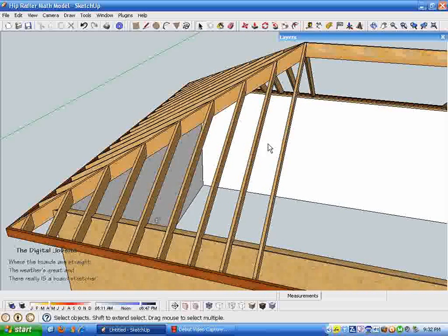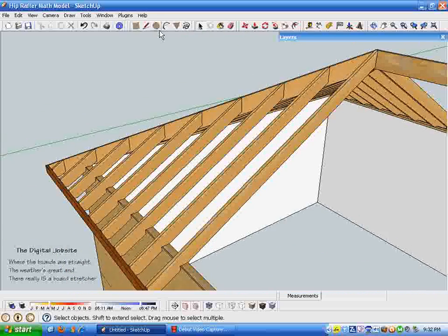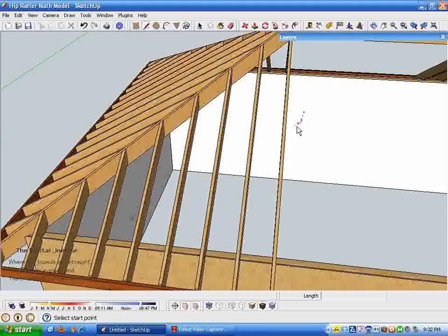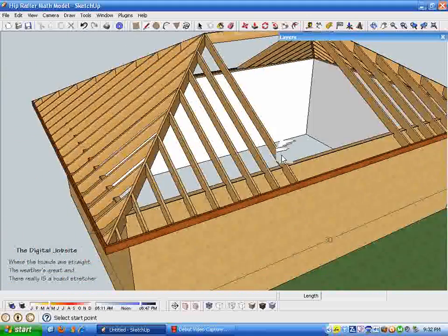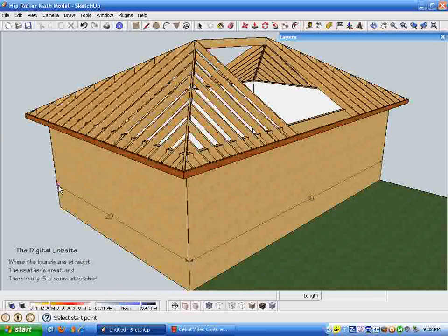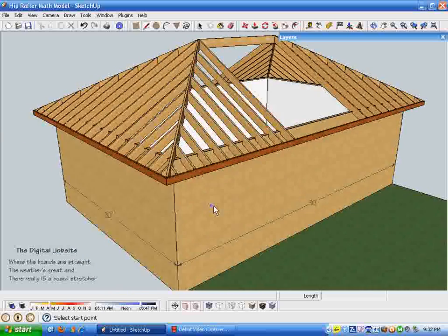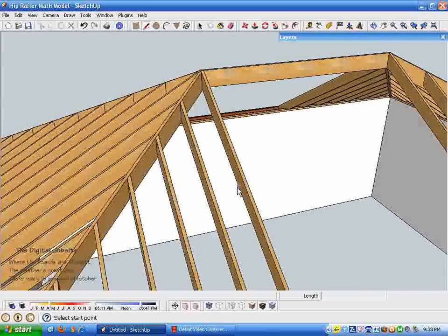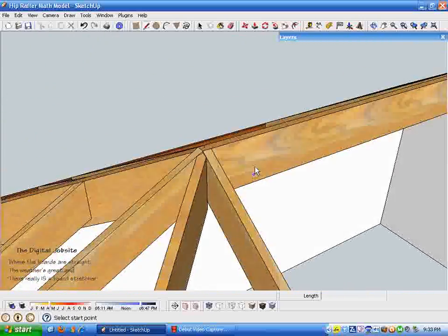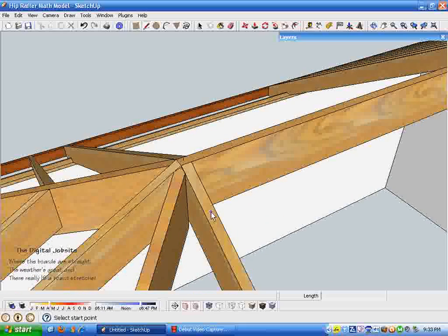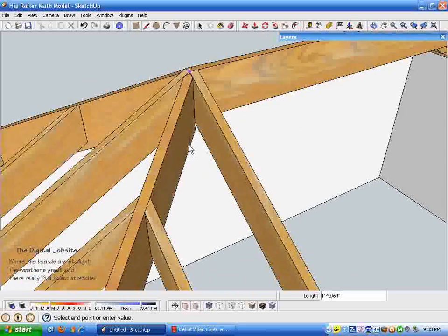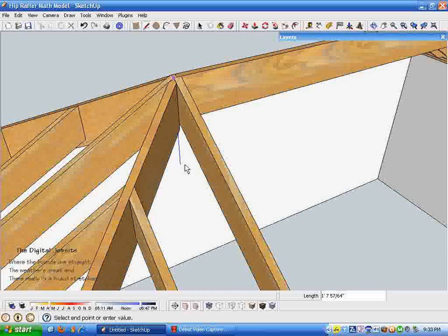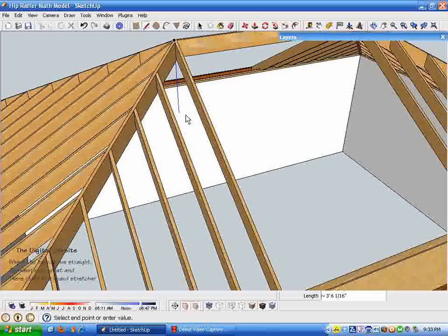And what I'm talking about is when you use a construction calculator and you enter the information for a common rafter length, for instance, you're going to start out with the overall span, which in this case is 20 feet, and divide it into, which would be 10 feet, and then subtract half the thickness of a ridge, which in this case is 1.5 inches thick, so you have to take off 3/4 of an inch from 10 feet, which gives you 9 feet 11 1/4, if I'm thinking straight.